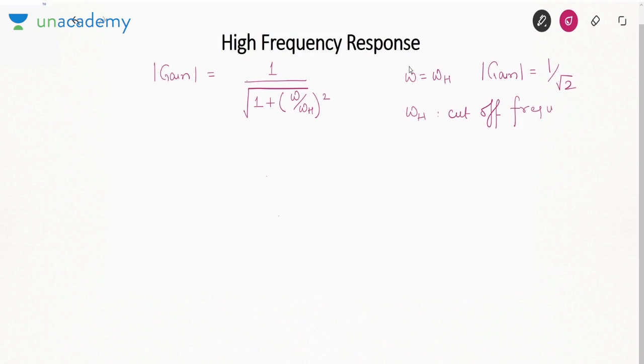So if you see the cutoff frequency here also, it is same, it is 1 by RC. That means the method to derive the cutoff frequency will also remain same. We will derive the Thevenin resistance across the capacitor, and then 1 by RC will give us the cutoff frequency. We can write down FH is 1 by 2 pi RC. Okay, that much is clear to you.